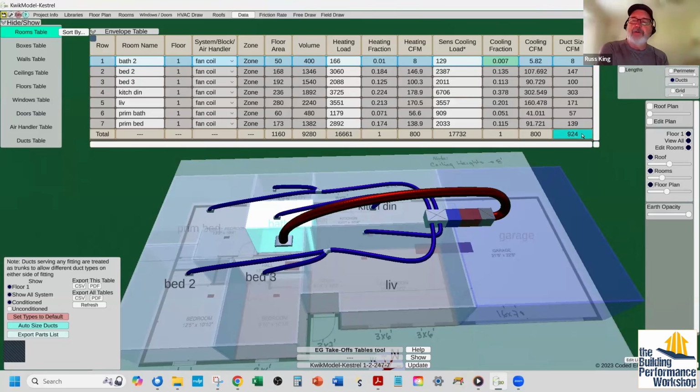The other safety margin in Manual D is that if the airflow you need isn't enough for one size duct, it goes up to the next size duct. Chances are that duct can handle more air than you need, but you had to go to that size because the size smaller wasn't enough. So every duct you install is going to have some excess capacity built into it, just by law of averages.